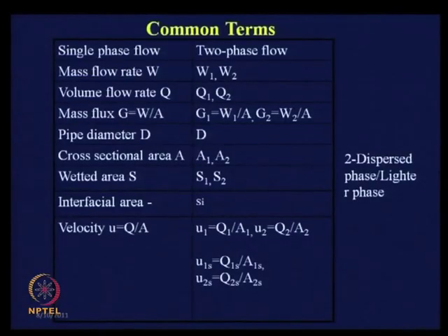So, it is usually the volume or the fraction of the total volume occupied by the heavier phase. Therefore, usually what we do for this particular case is, we specify it as HL. Now remember one thing, this HL or this alpha may not be constant throughout the entire channel. It may not even remain constant with time as well. There can be fluctuations with time, there can be fluctuations with your distance as well.